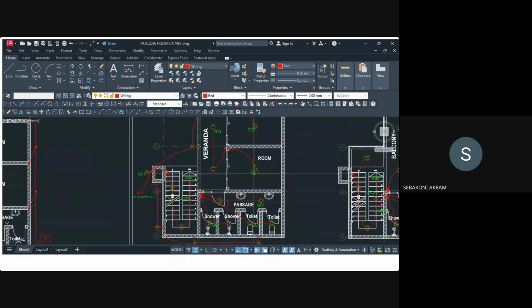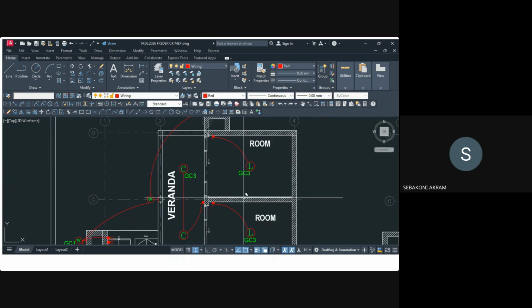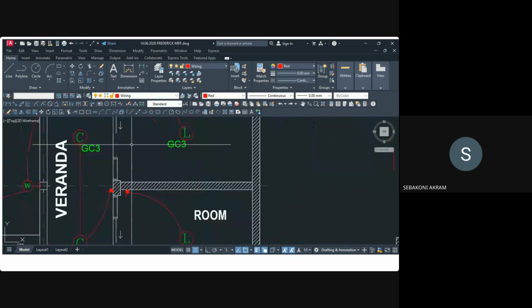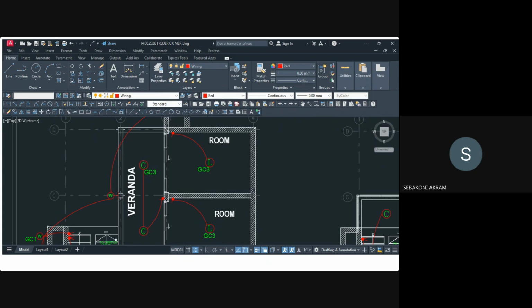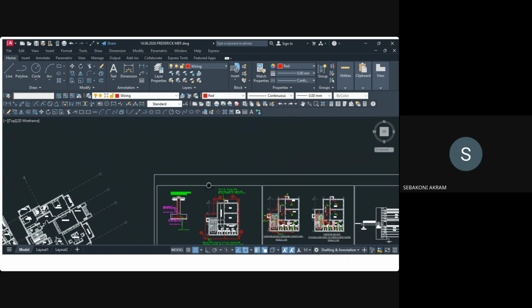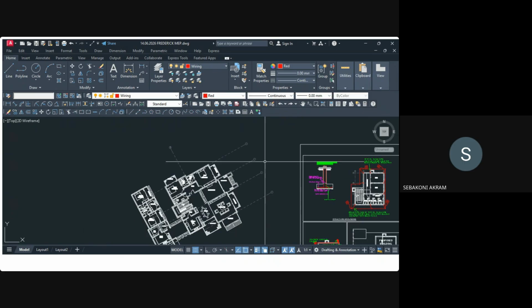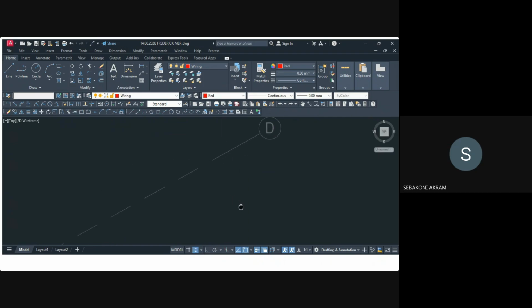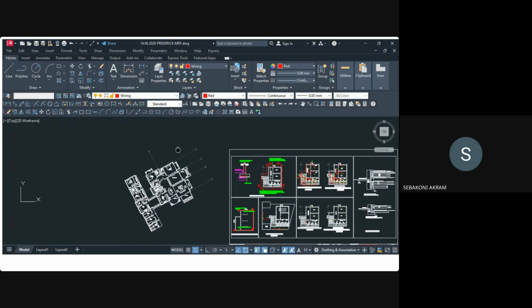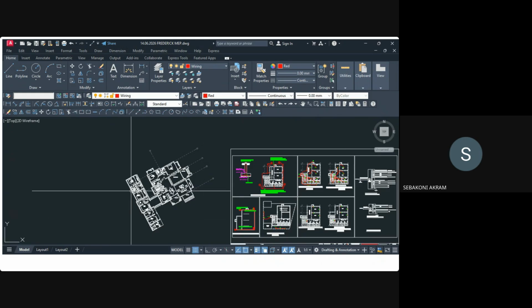So you can see now from this project, I had already designed my templates here. One reason why I purged the cleaned one, remember when I purged, I deleted some layers, not so? When I copy this and bring it to this other side, I don't bring all those initial layers that were within the first drawing, because here I have my own layers that I'm working with.